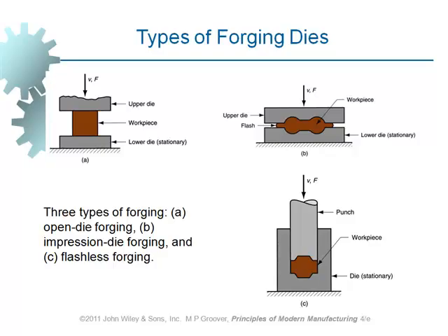And that one, which is impression die, then there is a cavity which has got the reverse shape of the desired part. And of course, there is a gap between the 2 halves of the die in order to accommodate the flash, excess material, which is left here. And this flash does play 2 roles indeed.